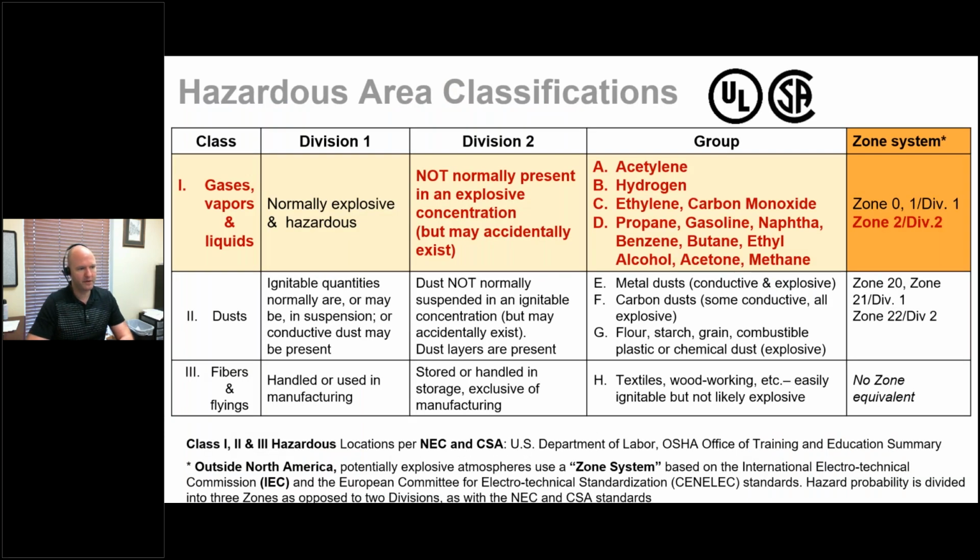So to talk a little bit about the hazardous locations themselves, this is probably the most important point to make: there are terms like explosion proof and intrinsically rated, and I'll talk a little bit about those, but the biggest theme for all of our products is represented here, in that these are Class 1, Division 2, which is how UL and CSA rate the products.